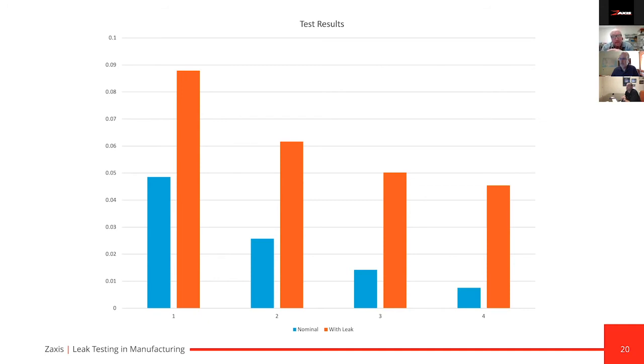It will come back to ambient temperature. It will try to return to close to what the virgin shape would be, and you'll get more repeatability. But if you had 10 or 20 or 30 parts, you could start running each test, and by the time you came back to the first one to do repeatability, it would be back to more of what you would expect the first time. So it's a common thing that will happen if you test a part multiple times.